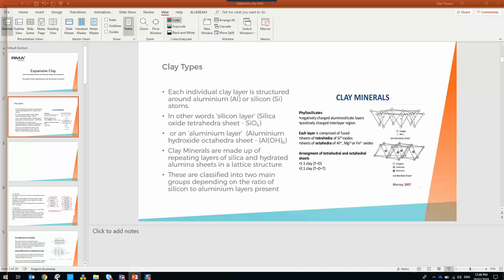The other one is people just want to build a fill platform and reduce the YS, the surface movement. A typical black soil has a shrink swell index, which is the Iss, if you see that in soil reports, of about 6. So in Dalby, with that climatic condition, that equates to about 130 mil YS.